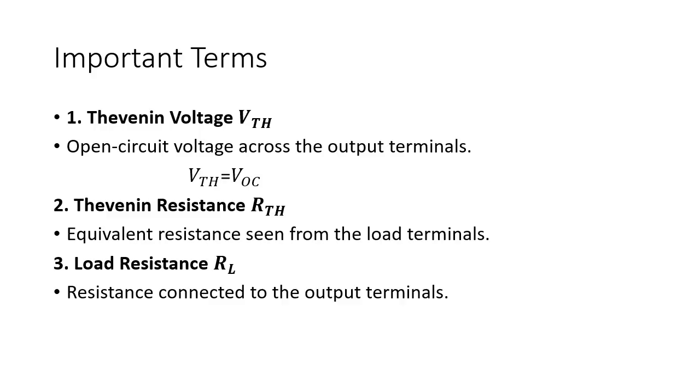The important terms used in Thevenin's theorem are Thevenin's voltage VTH, Thevenin's resistance RTH and the load resistance RL. These are used for the calculation of the Thevenin's equivalent circuit. For the Thevenin's voltage, we find the open circuit voltage across the output terminal.